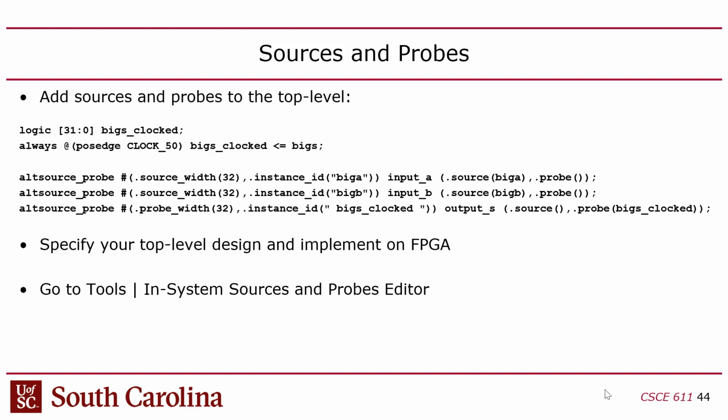But that will actually create a module, but instead of having it as a module, you're actually referring specifically to the physical LUT primitive on the FPGA fabric. And the same thing goes for RAMs and DSP blocks and I/O buffers. But in this case, we're also doing this alt source probe is a physical piece of hardware. And then it's really easy to use, actually.